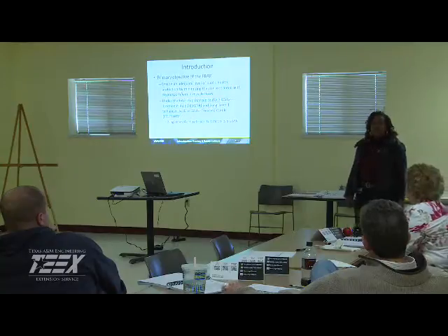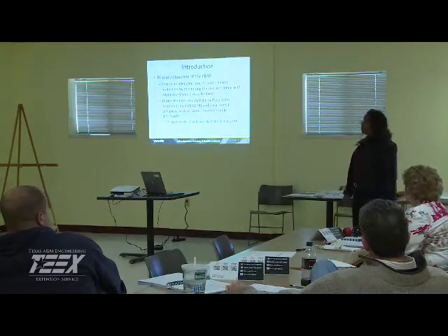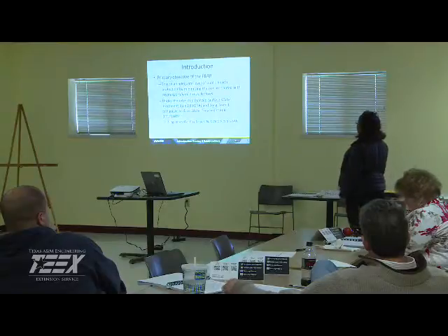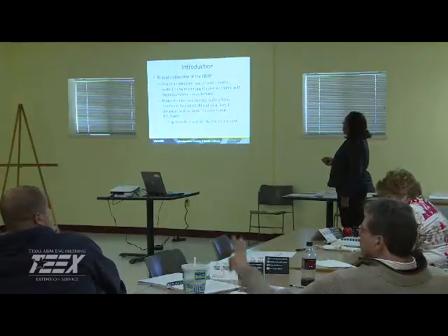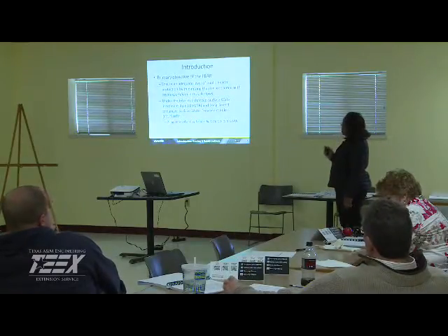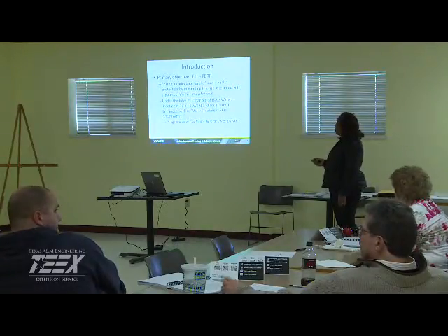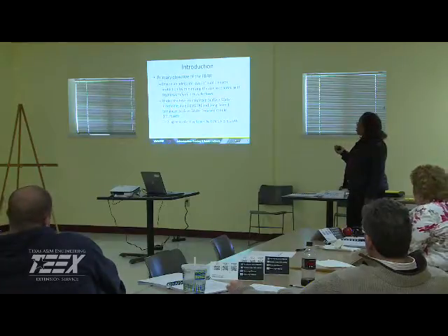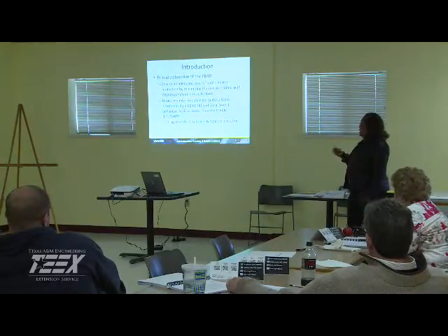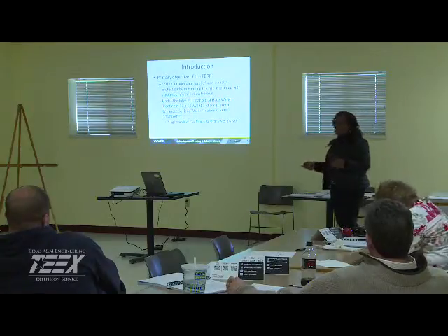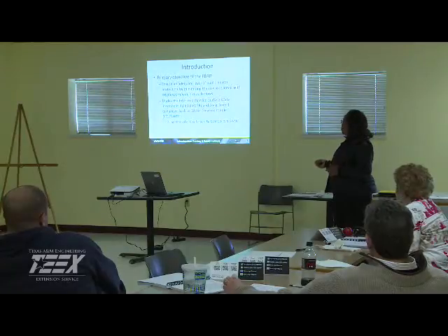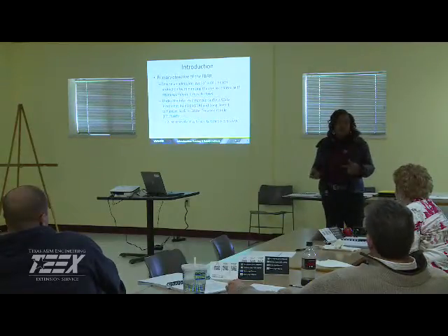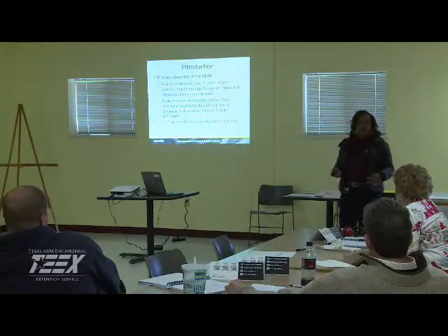Yes, it is. So the way to reduce these is filtration. The primary objective of the filter backwash recycle rule is to ensure an adequate level of public health protection by minimizing the risk associated with cryptosporidium in your recycle flows. Under the Interim Enhanced Surface Water Treatment Rule and the Long Term 1 Enhanced Surface Water Treatment Rule, you have to be able to demonstrate at least a 2-log removal of cryptosporidium for your surface water and your groundwaters under the influence of surface water.